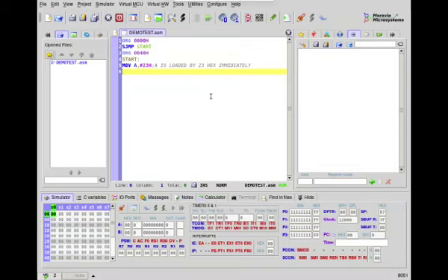Then after I am writing another instruction, say mov B, #45, only 45, nothing H. Then after I am writing add A, B. So A and B are added and the answer is available in A. Now the microcontroller is an embedded system, so all the program is running continuously. So we have to write here sjmp here.